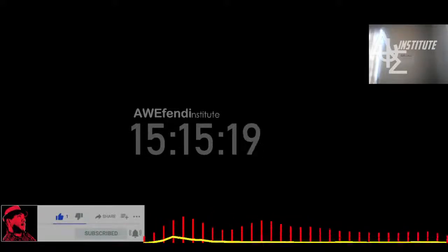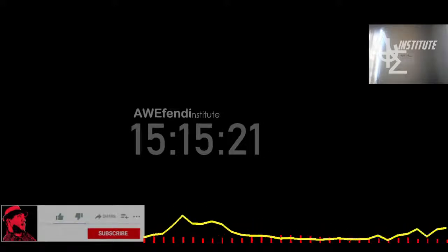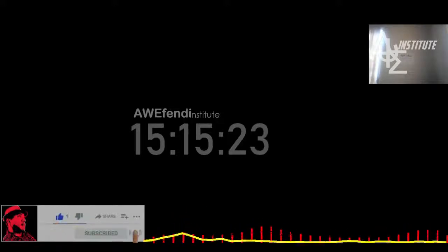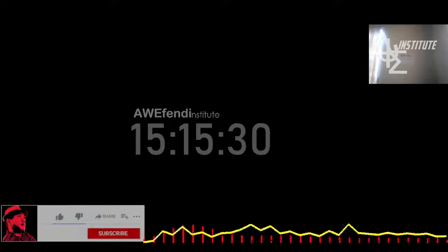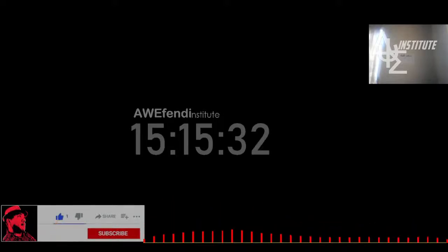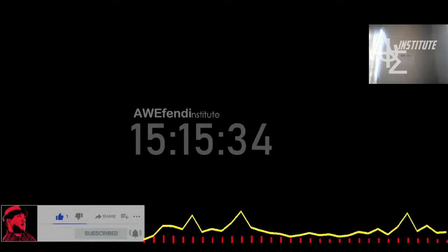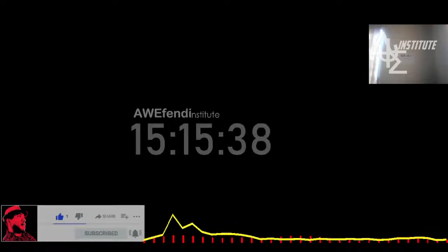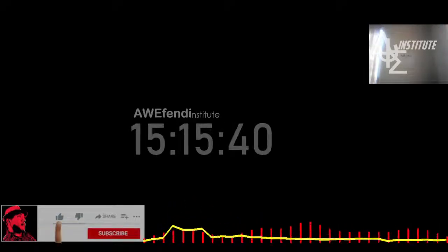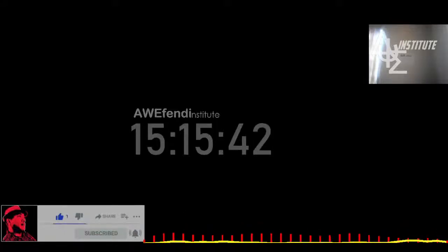Volume extract, we can preview the inside faces. Oh yeah, here I made a mistake. Let me show all again and do the exact same thing, because there it wasn't closed off on the top. There we go. So now it's contained in there. Preview looks pretty good. I can confirm by clicking on the green check mark, and then I can start setting up the boundary conditions on the fluid part.